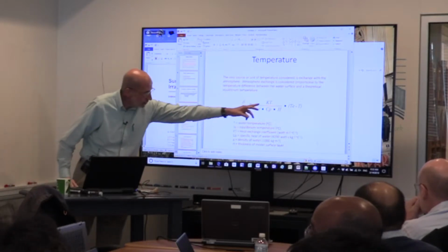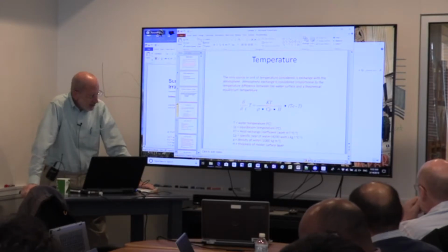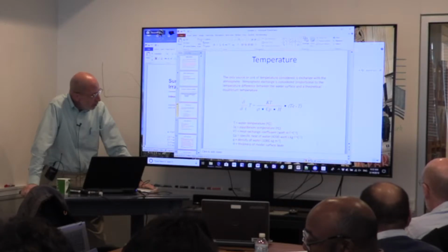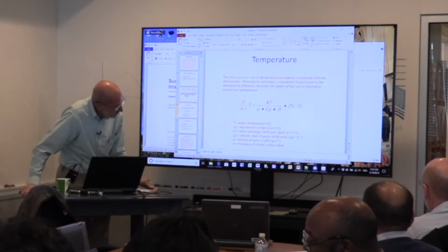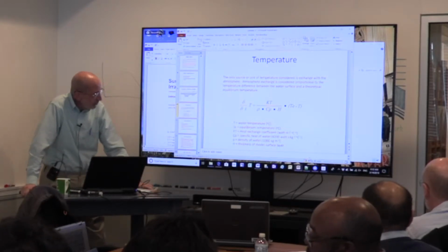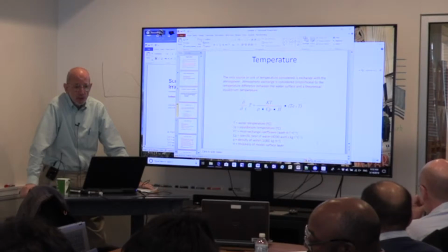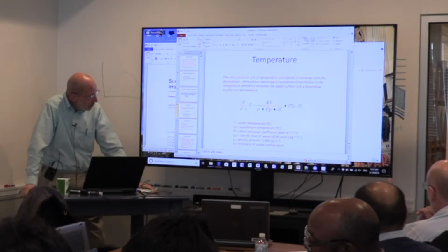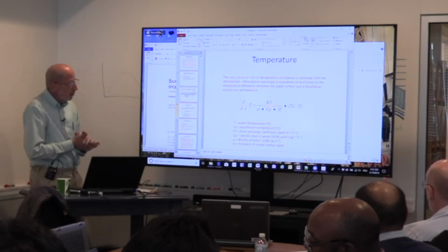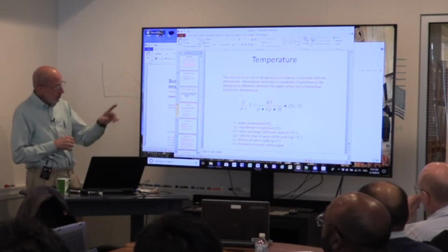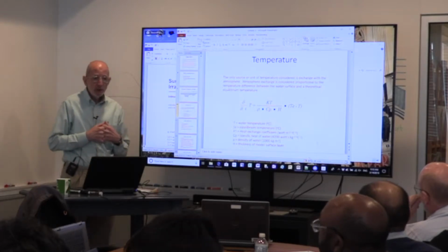And then there's a rate constant, KT. The units of KT, I think, are watts per meter squared. Oh, there it is: KT, watts per meter squared per degree centigrade. So this rho CP, what we've got to do is take watts and divide by the specific heat of water to make it appropriate for our model variable, which is temperature. So your goal, if you will, is to derive from meteorological observations the equilibrium temperature and the heat transfer coefficient, KT.